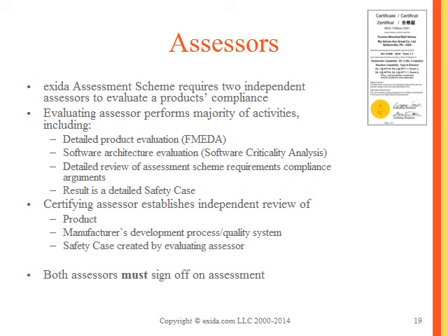That evaluating assessor will also review all the compliance arguments that a manufacturer may have, why they meet the assessment scheme requirements. So why are they compliant with IEC 61508? For example, if we go back to that software design architecture fault detection, for SIL 3, that was highly recommended. Give a good argument, show evidence why you meet that particular requirement to say, yes, your development process meets the requirements of SIL 3.